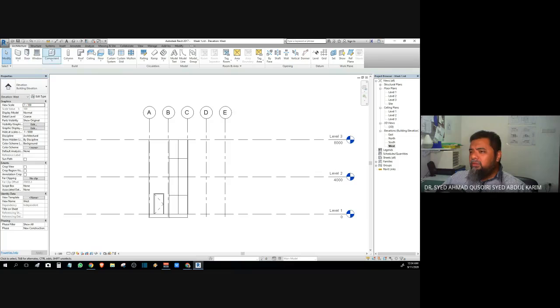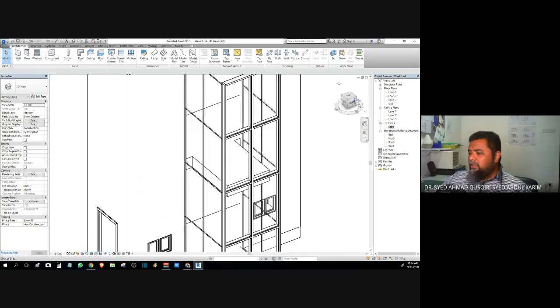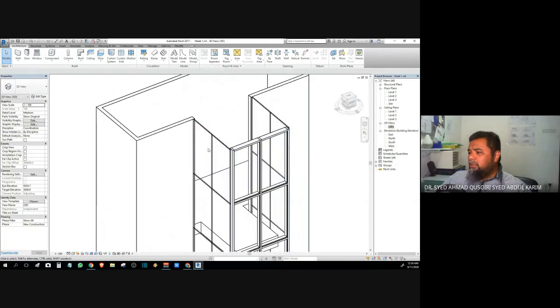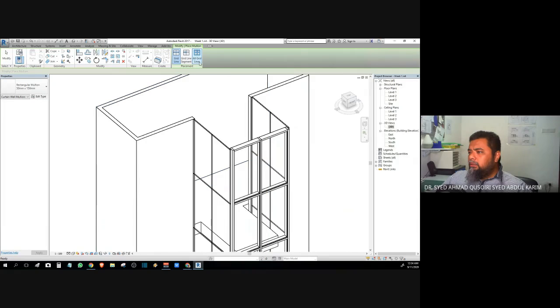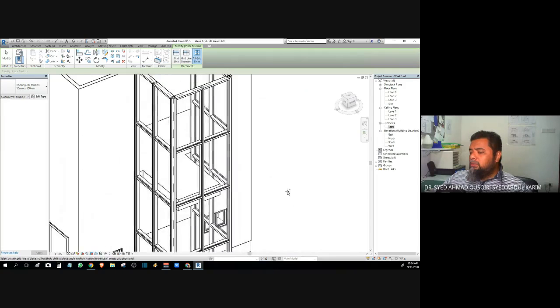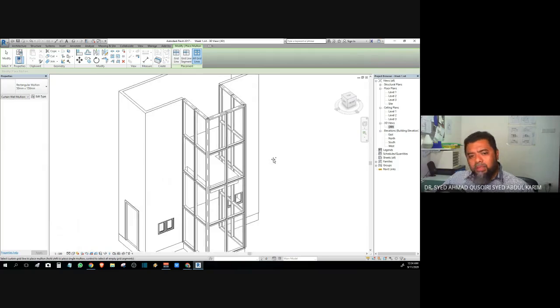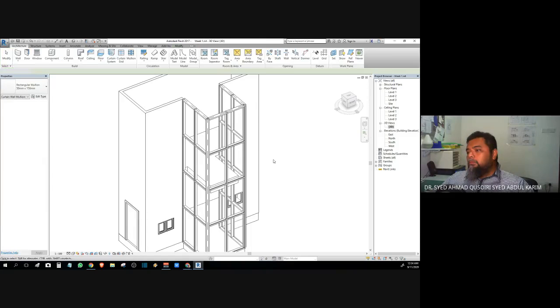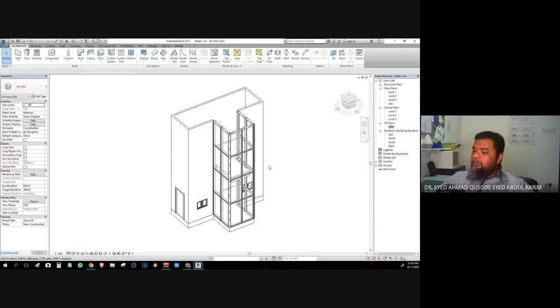Okay, you can do this in 3D. 3D also no problem. So you can see that's my frame or my mullion. This is still in grid. Mullion, all grid line. I'll click here and here. So you can see now our curtain wall is equipped with mullion. However, if you look very closely, it is not really that complete yet.